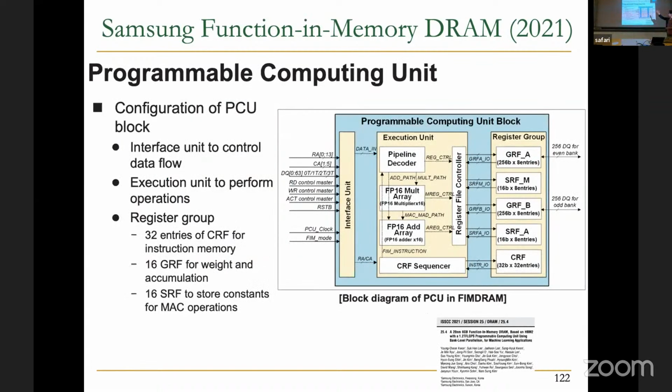And those processing elements are something like this. They are called programmable compute units, and they are relatively simple. One of the reasons for that is that they are specialized for a certain type of applications, artificial intelligence, neural networks. And for these applications, what you need a lot is computation with matrices, matrix multiplication or matrix vector multiplication, right? So if you need to do that, multipliers and adders is what you need. And if you are operating on entire matrices at the same time, you can perform many dot products, many multiplications, many additions at the same time.